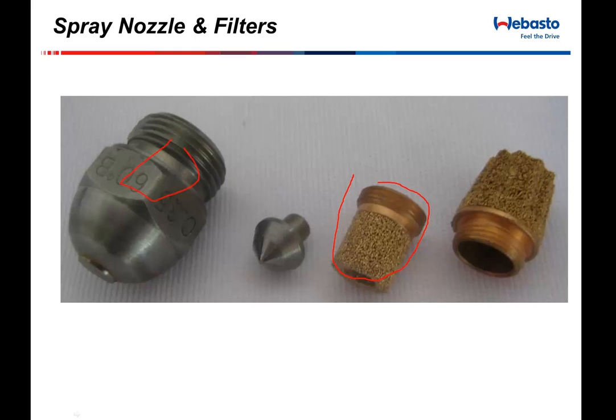In the long term, it's more of a Band-Aid than anything, and will require to be replaced over time. The longevity of these nozzles really goes hand in hand with the quality of fuel that the fleet is operating. If they're buying good quality fuel, I've seen nozzles go 7 and 8 years out there. If not, there's fleets that will be replacing nozzles 2 or 3 times a season.